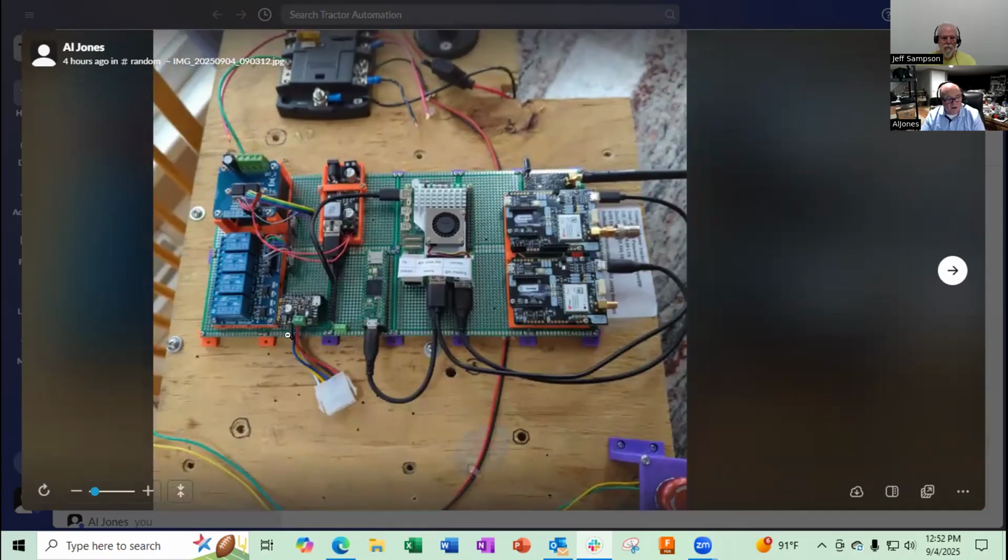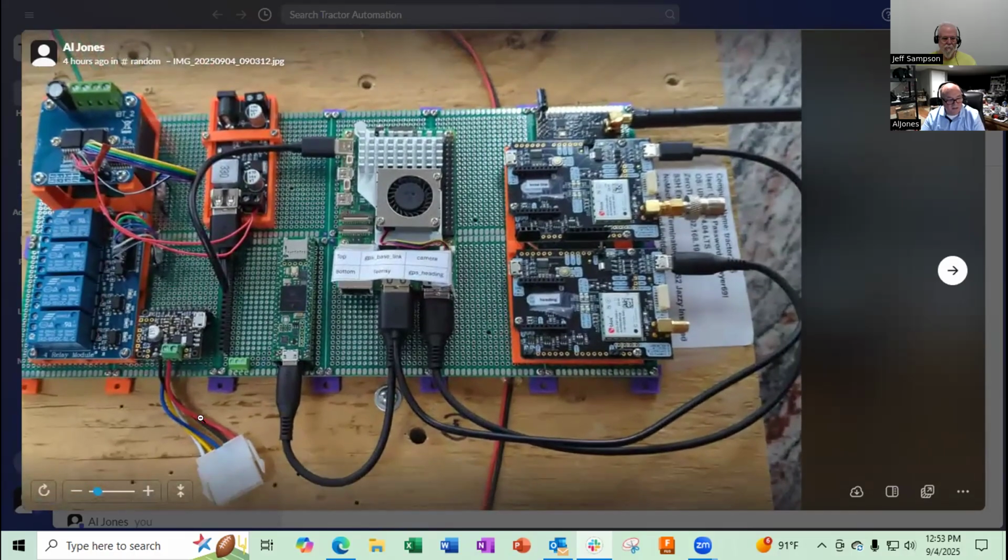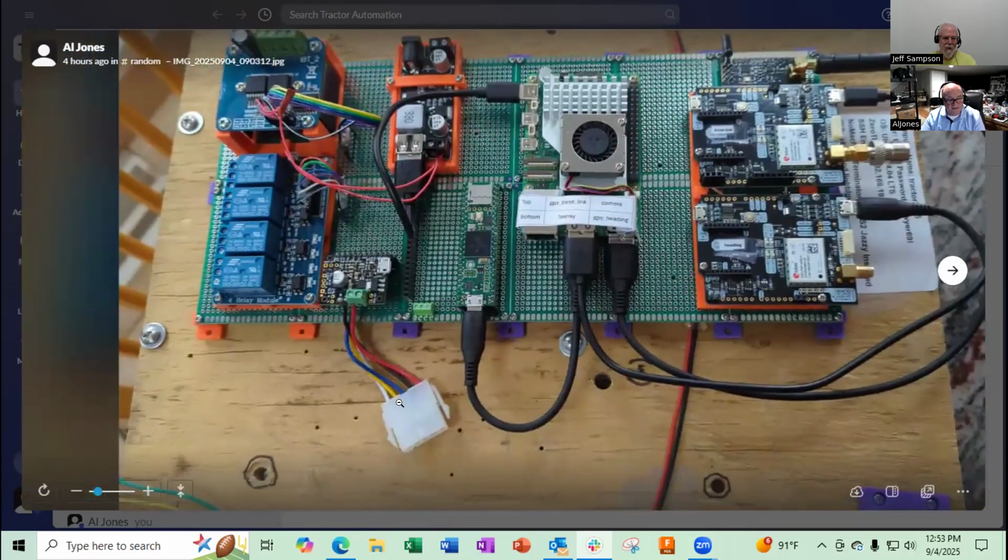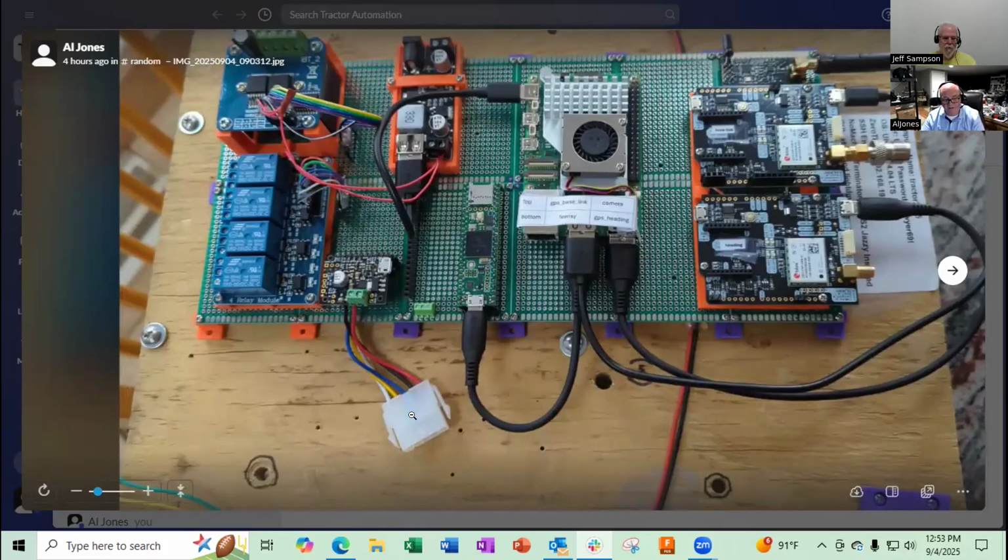I was working on the wiring for this JRK motor controller and just went ahead and hardwired it. This is a 5-pin header for the linear actuator, and there's power and ground for the motor, and then there are 3 control signals that go underneath it. I hardwired that in to avoid having loose connections.